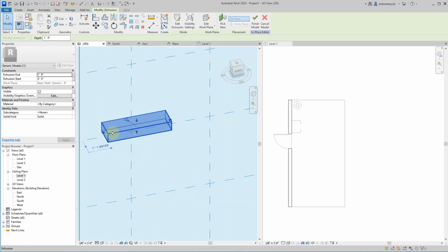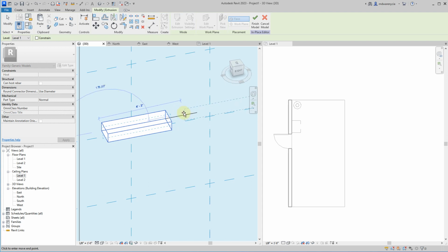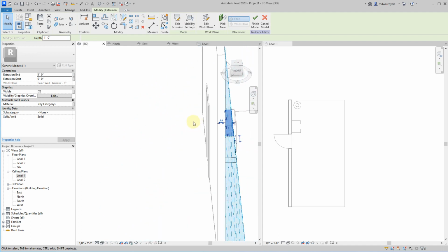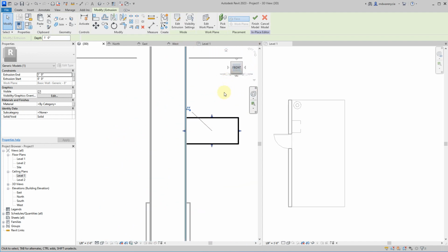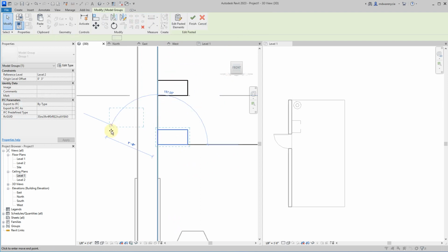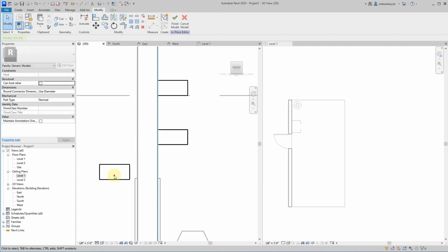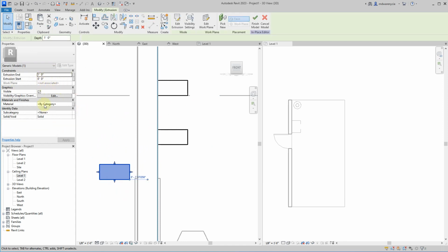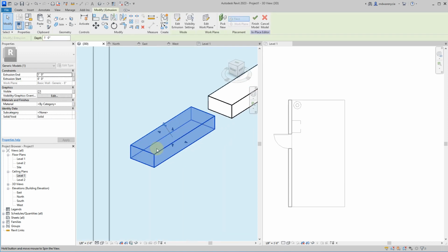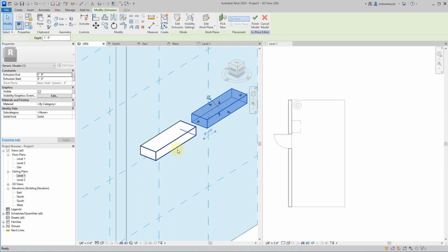Let me see if it'll let me copy this over. This is one way that you can actually break extrusions too: you can copy them and move them over from different planes of view. So I can move this down here, and you can see it's not associated with a work plane now. So you can get it away from that sort of thing, but try not to do that initially while you're still learning. Anyway, I was going to set this one to extrusion end at, let's do -2 feet.